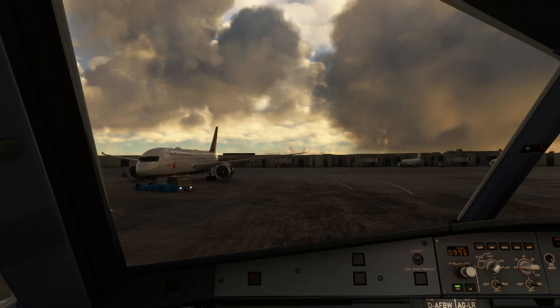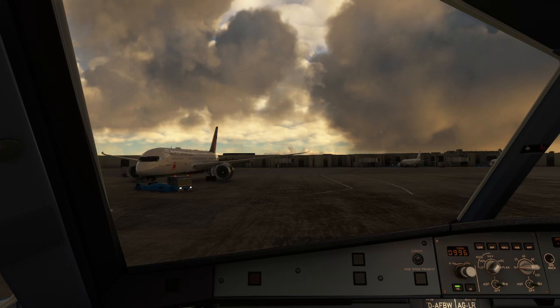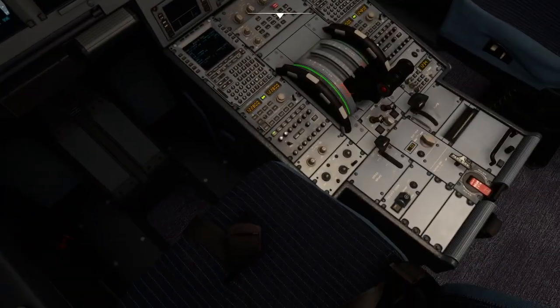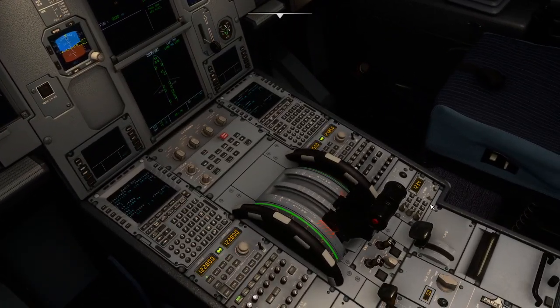Okay, right now I got the clearance via PDC. Sri Lankan 104 clear to Brussels, runway 27 left via Bravo Papa Kilo 7 Golf departure, squawk 6010. So let's go ahead and configure the squawk. As I said, it is 6010. Click on ident, so 777, that way clears behind, right turn. It will be identified, and the initial climb we have been given is 6,000 feet.